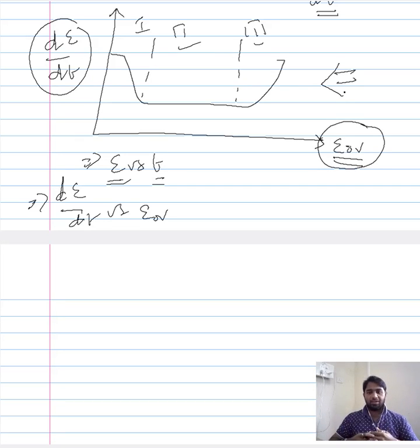Of course, we were able to arrive at this plot from the conventional creep curve, but we saw that by considering the overall creep strain, we can independently plot this curve. Now the reason for having different representations of creep is that we are considering several factors while plotting the creep curves or while studying the creep behavior of the material.